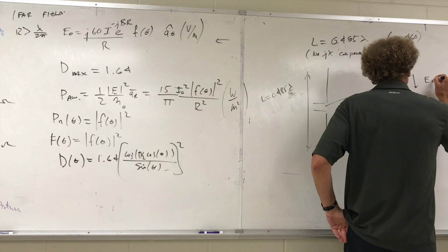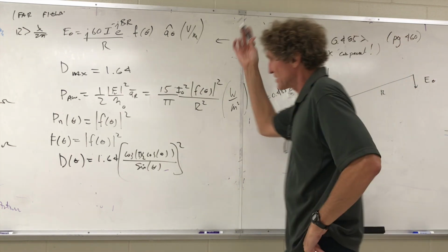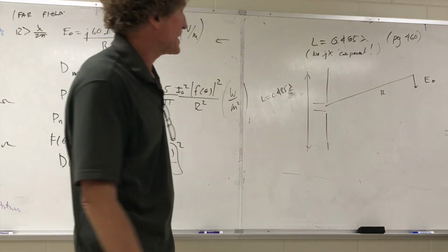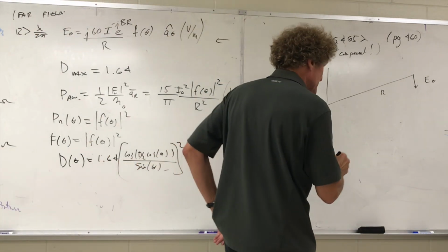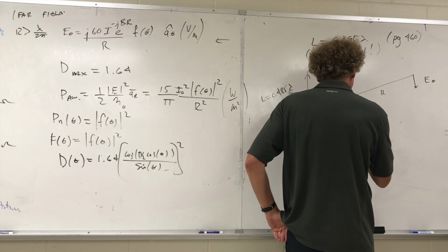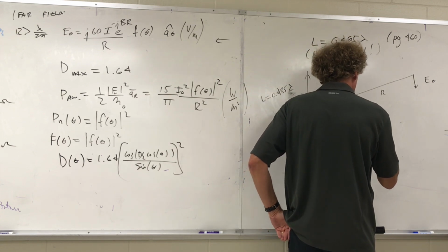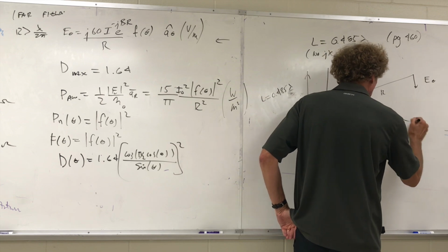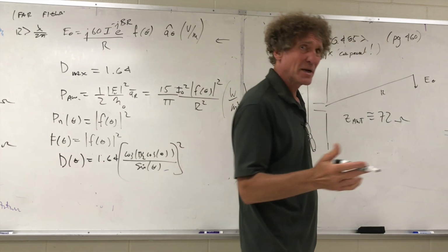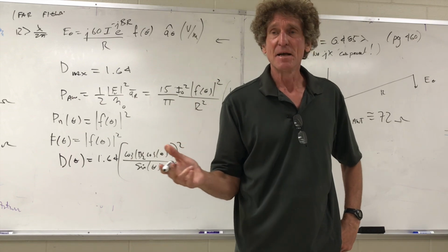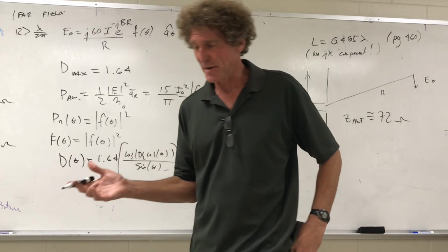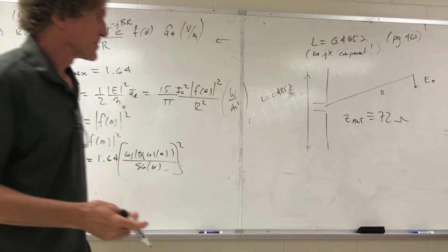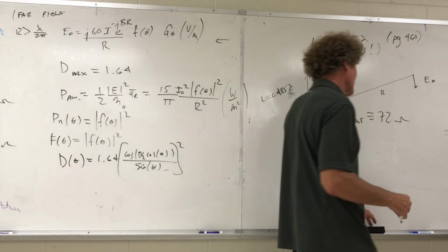Anyway, if you take a look at this, if you're in the far field, all the field components, E theta and everything like that, is identical, gain, everything, to a half-wave dipole. The only thing is, the actual impedance, and this is the thing you write down, the Z antenna is about 72 ohms. Now, he'll have, I think, 73 ohms. Does he have that, or 72? But I think he has 72, but I don't remember. You see it in there? 73. He has 73. This is one of those things, different books have different things.